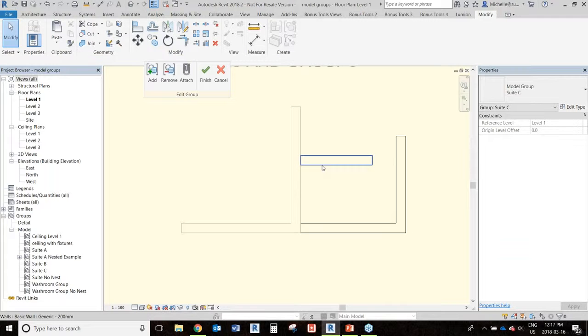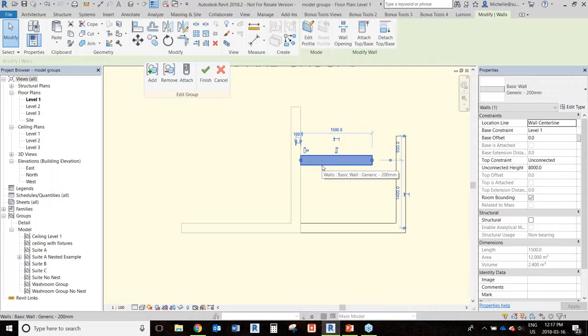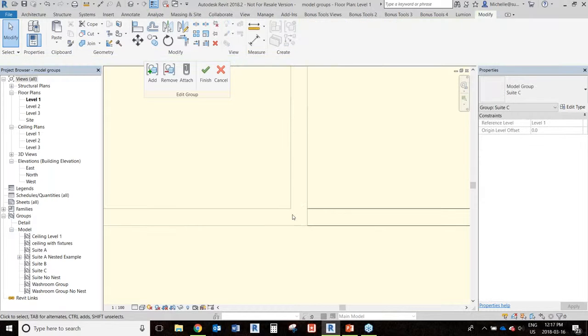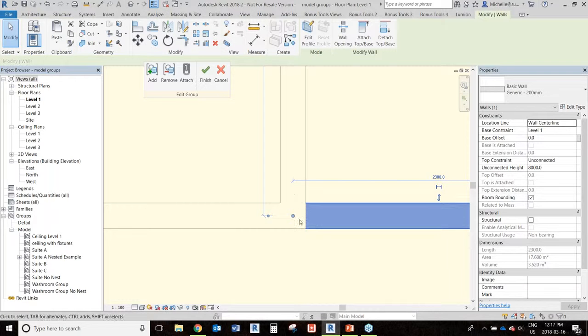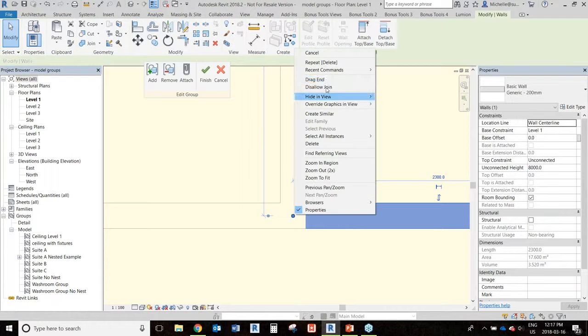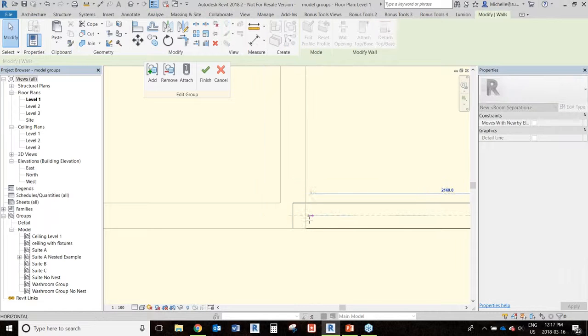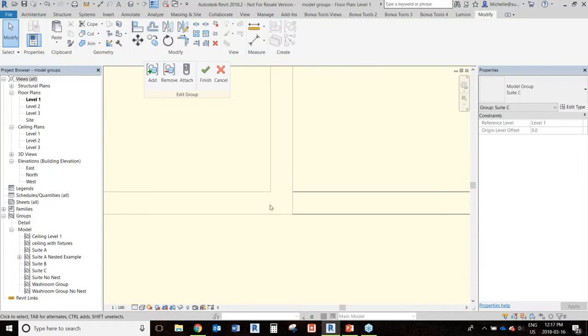There was one case where I worked with a client who had a very similar situation to this, where they were editing and adding a wall that was joining up with a corner of another group. And just the fact that they first allowed the join and then did the disallow, it was still giving them a fixed groups warning. So we just tried for fun.